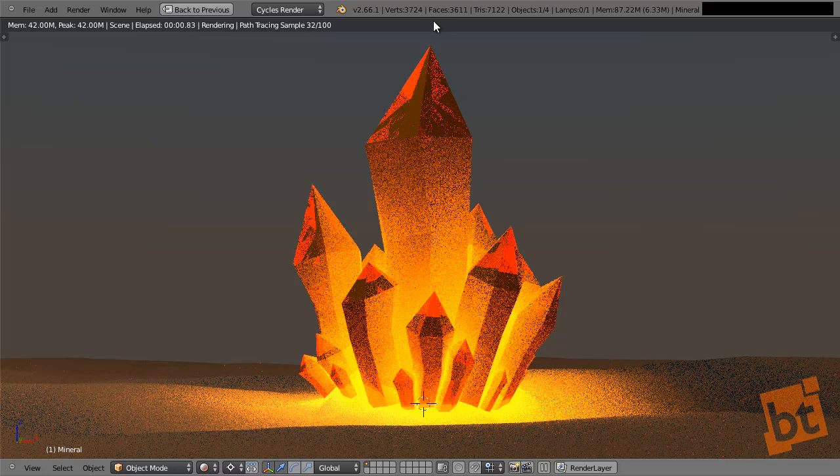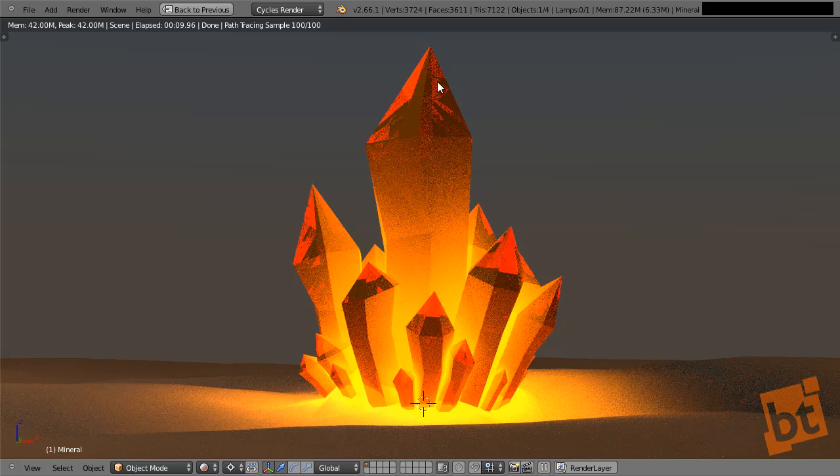So now I will take a quick render with more samples, because keep in mind that this is a material that will give a lot of noise, right? Because there is emission and there is glass, which are the shaders that are more difficult to get noise free. So we will get a lot of noise and speckles and weird stuff. We are also playing with very high values of emission here, going through transmission in the glass. It's a crazy material, so it's very difficult to get it right without any noise. But we will clean a little of that noise later in the compositing.